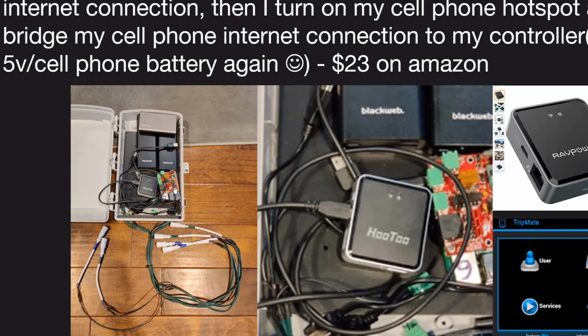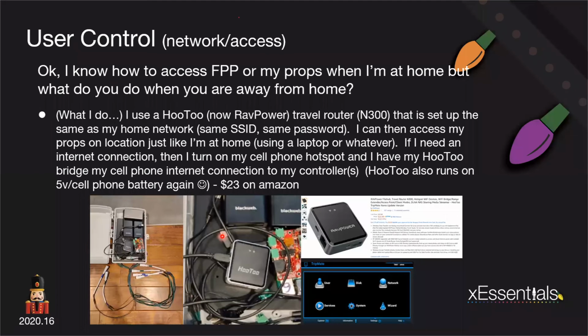And the Pi is just providing data and ground for my pixels. And this box I just keep around. The reason that I do use the Pi with the Pi hat in this particular case is because it is easy to disconnect and connect directly from the controller versus using the JST connectors. Thought I'd zoom in and give you a little bit of extra on that one.